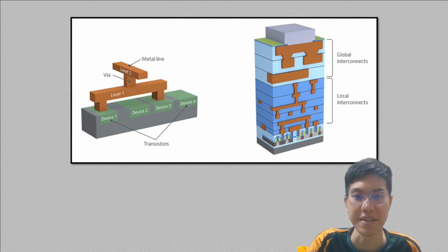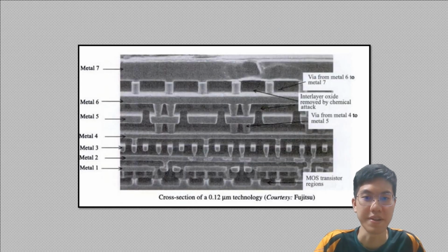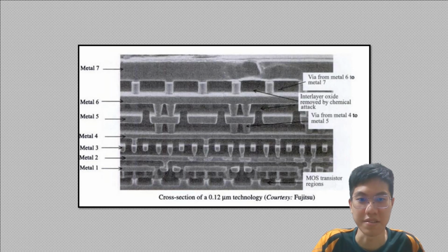Metal layers help alleviate some of these problems by giving the ability for the routing to take place in 3D space. These layers specify the level at which the metal lines can be placed. The metal lines at each layer are connected to the upper and lower layers by structures known as vias, which act as the bridge between wires on two layers. The number of metal layers depends on the foundry and the technology node used. For example, 7nm TSMC technology node uses 14 metal layers, while 7nm Samsung technology node uses 30 metal layers.